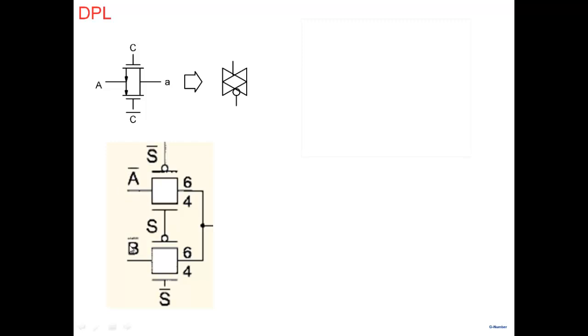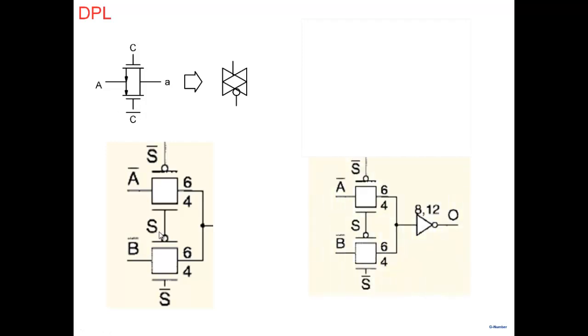For example, if you look at a transmission gate, if there is an S, there's an S bar also required, right? And as I said, you can make this logic better by putting an inverter at the end of each one of them. If you put an inverter and then you cascade, then cascading becomes easier. You don't get a long transmission line.